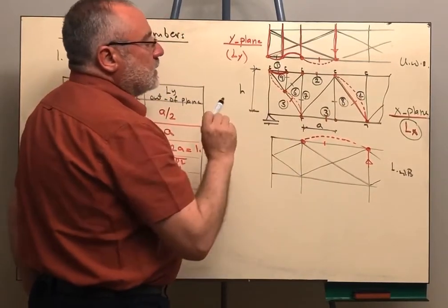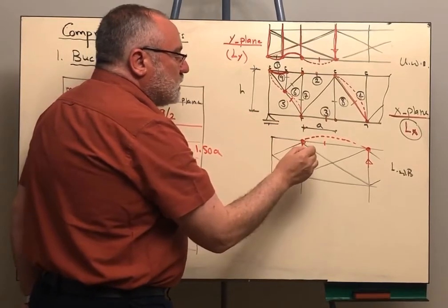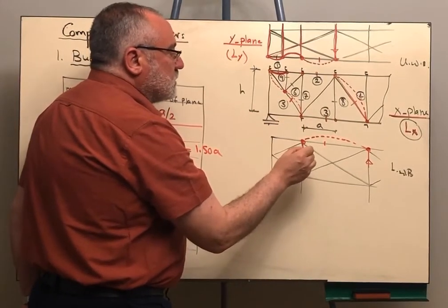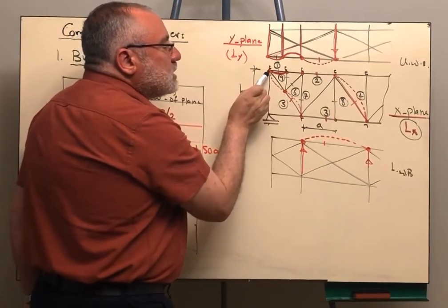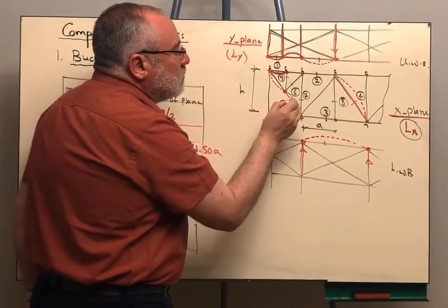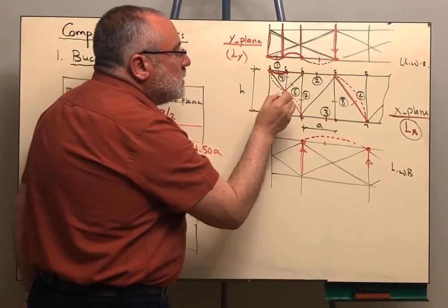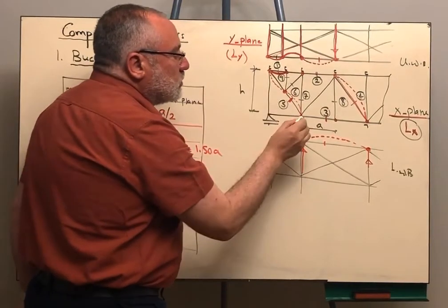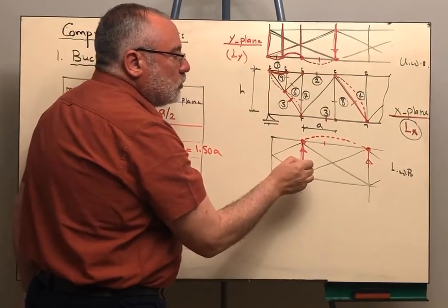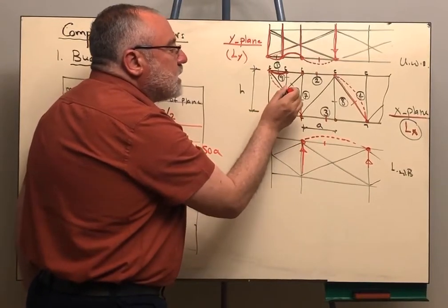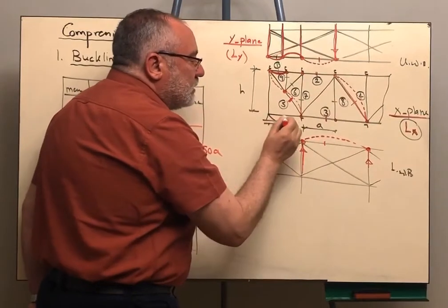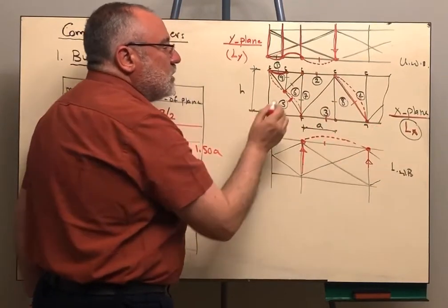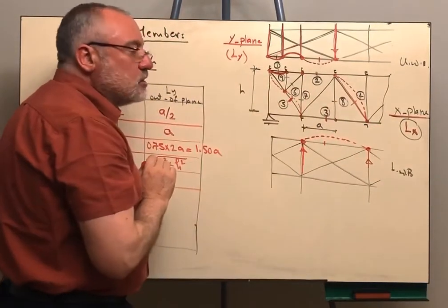Again, now this point is braced by the effect of the strut, and this point is braced by the effect of the purlin. But this is not the end of member 5. Member 5 is here. We are talking about this point. This point is braced due to the effect of the lower bracing, and this point has nothing to hold it, because I'm having a strut in this level and a strut and a truss in this level, and we don't have anything, of course, in the middle.